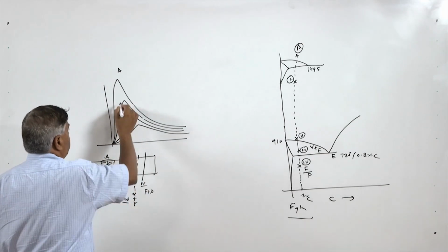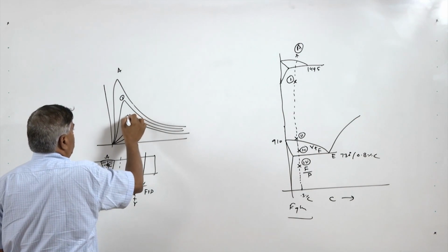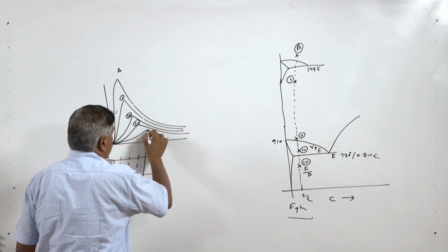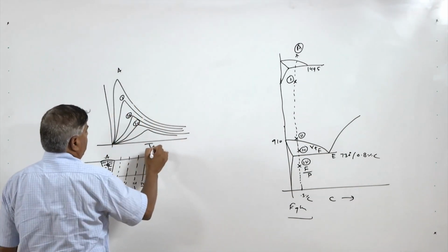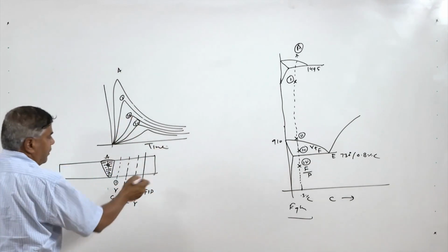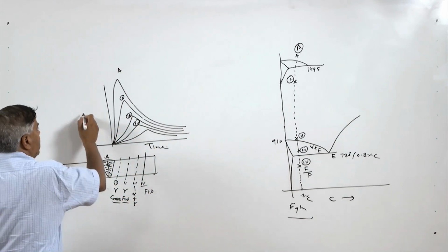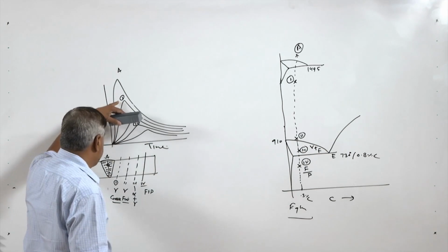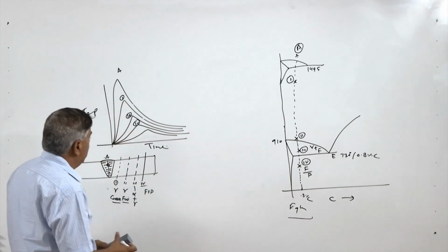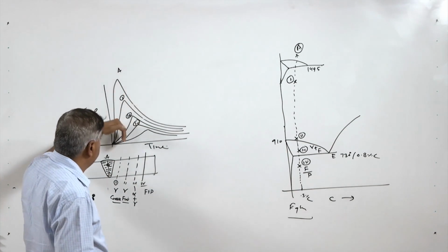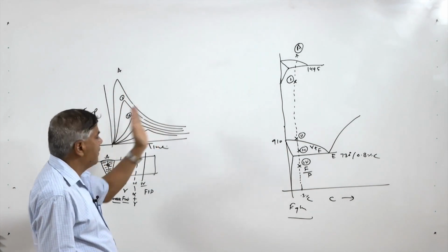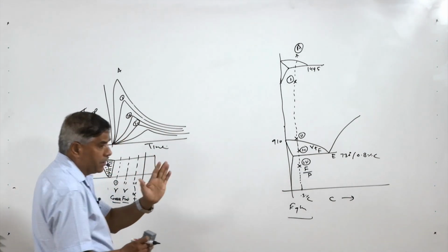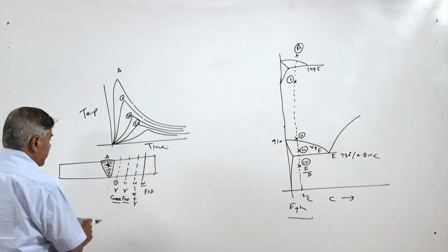If we look at the weld thermal cycle for 3 or 4 different zones, we will see that point 1 experiences a much higher temperature compared to points 3 and 4, but it takes a shorter period to reach there, and a longer time for reaching the lower temperatures at the points located further away from the fusion boundary.